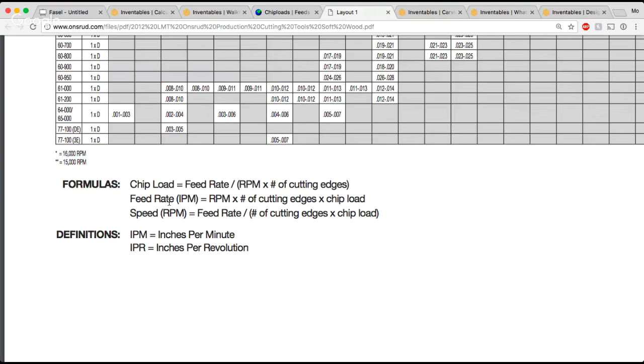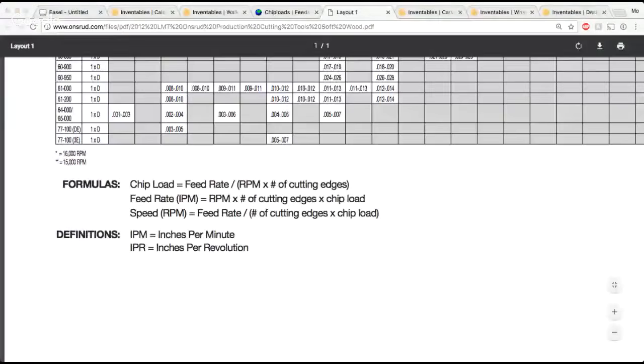Now, again, it's important to know the limitations of your machine. I think I've talked about this a little bit in this episode, but a lot of these manufacturers, especially Entreprenuer, are selling these bits to people who have massive CNC mills, and what those bits can do on those machines is much different than what the bit can do on your machine. So when you're calculating this and you get a number that's outrageous, you should use a little common sense and be like, I really don't think my machine can go 150 inches per minute. That seems a little extreme. Maybe I'll tone it down and try 50 inches per minute and see how that goes.